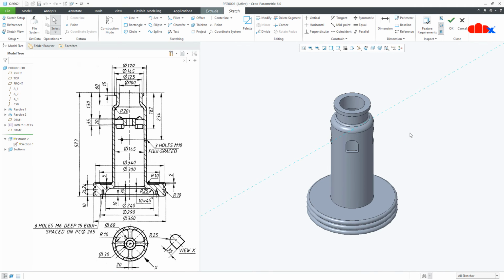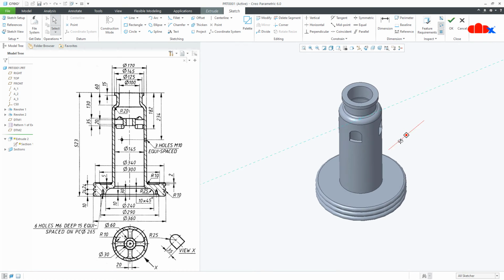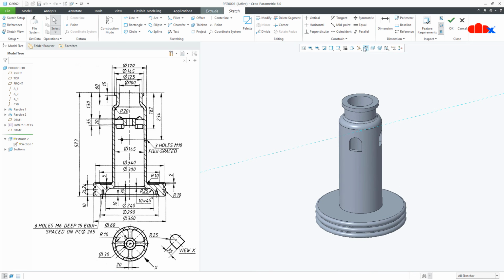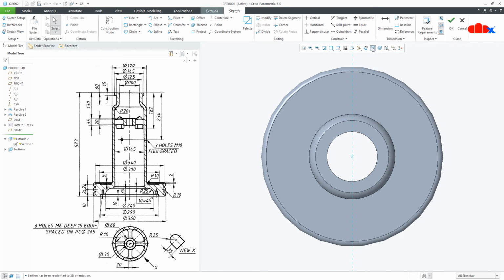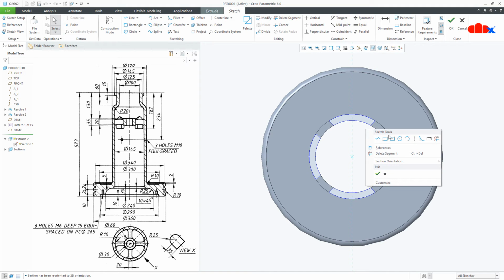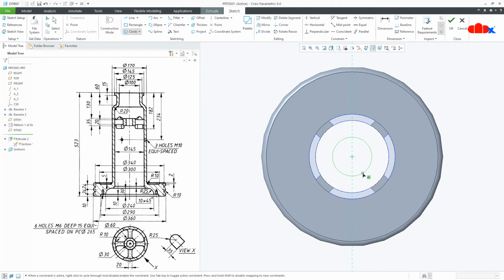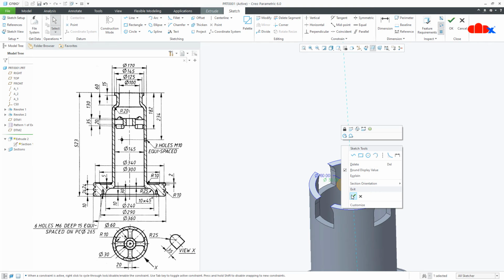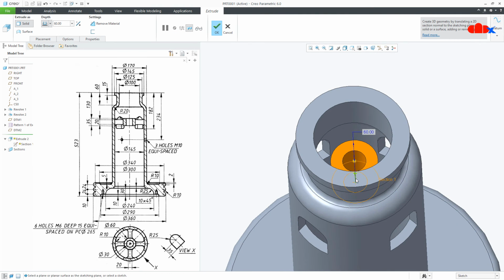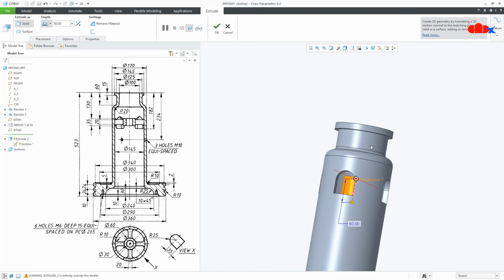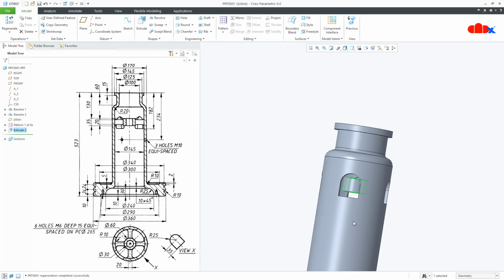Sketch. So automatically it will move to that plane. Normal, clip model. Now draw the two circles just like this. Now assign the dimension. So this is dia 60 and this is dia 30. Say OK. Flip the material direction and the thickness is 35. Say OK.